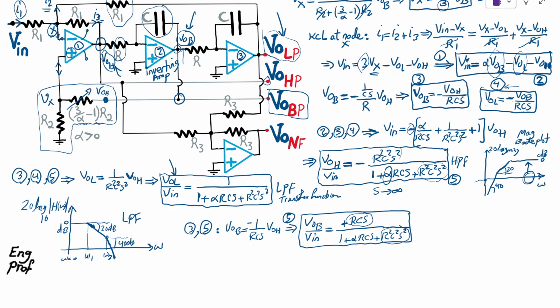and the dominant terms in the denominator are R square C S square. Therefore, the whole thing converges to 1 over RCS when S goes to infinity, which again, at super high frequency goes nearly to 0. So high frequencies are not passing either. Therefore, only a band of mid frequencies are passing. Therefore, this is a signature transfer function in the S domain for a bandpass filter, and effectively it makes sense because it is obtained from a cascade of low pass and high pass filters.